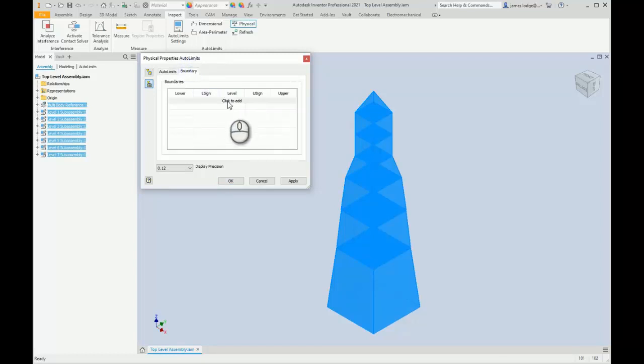So I'm going to hold down Alt and click to add. This adds in all the attributes. However, I want to have a serious upper attribute, so I'm just going to add one more in here. So less than approximately 10,000 kilograms. I'm then wanting it to show me this red indicator if I breach 5,000 kilograms. So between 5,000 and 10,000 kilograms, I will get the red indicator.